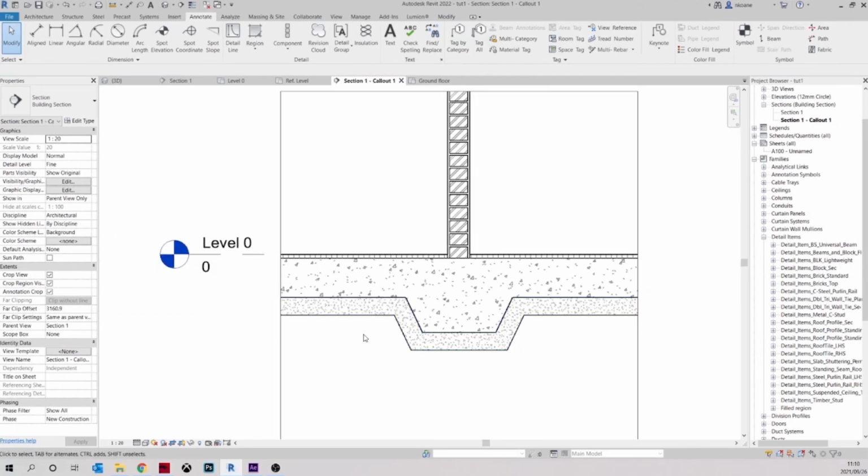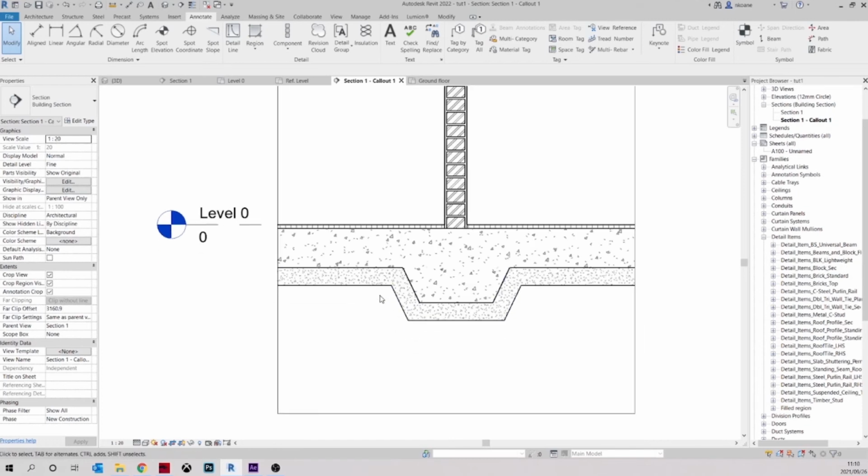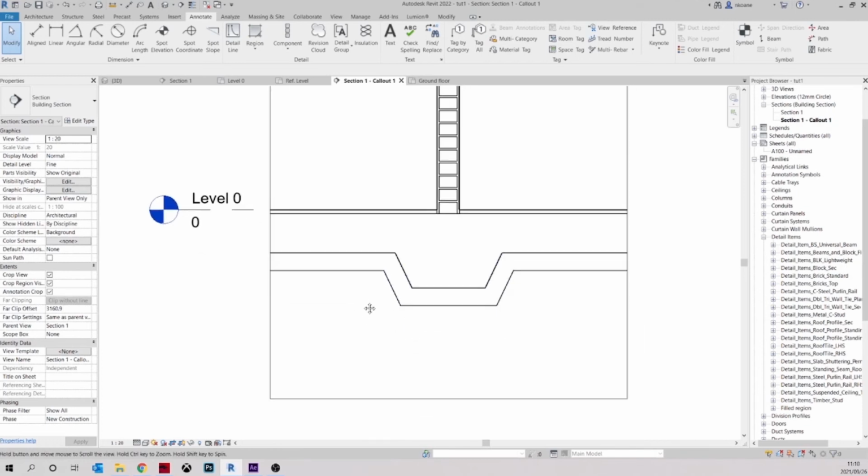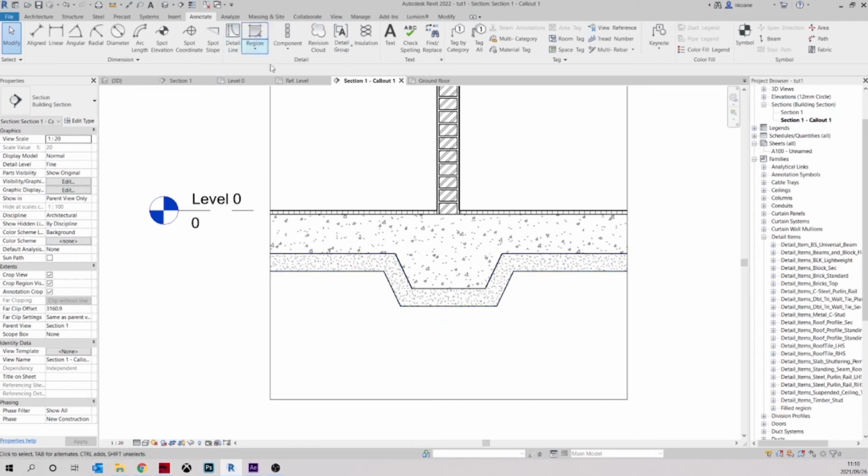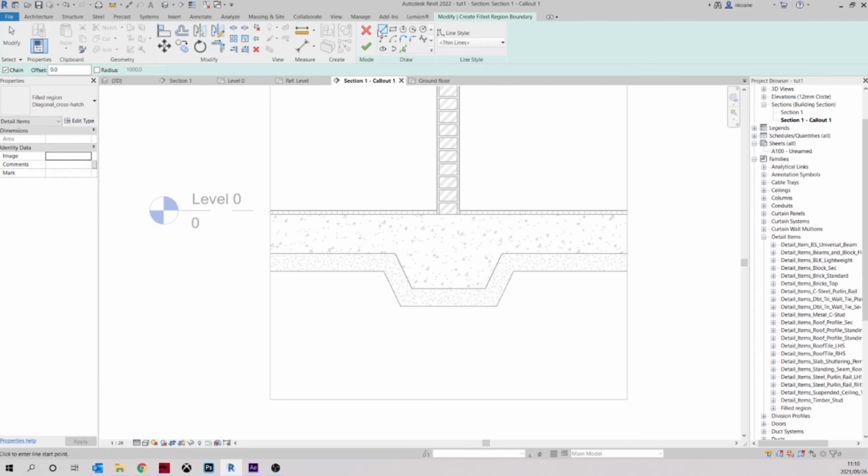After that, you want to put your layer for compacted fill. It's the same process again. Edit region, new region, you can draw that out like that. Close it here, close it there, and this one we're going to bring it this side and close it here.